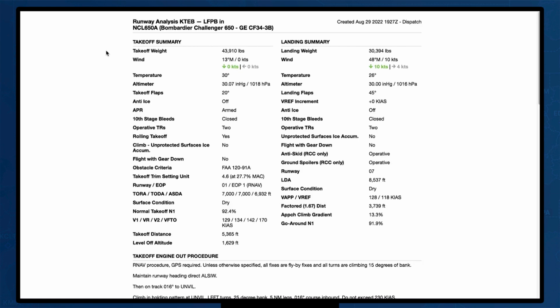Yeah, for sure, Caitlin. So this report is extremely useful because at a glance, it gives the flight crew the opportunity to view takeoff and landing performance and all the assumptions that go with it. And by assumptions, I'm saying landing weight, takeoff weight, the winds at takeoff and destination, temperatures, any sort of aircraft configuration.